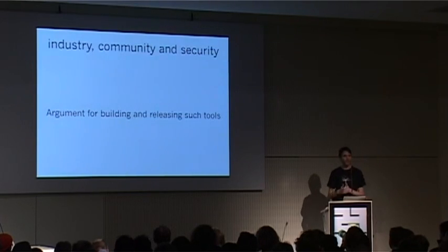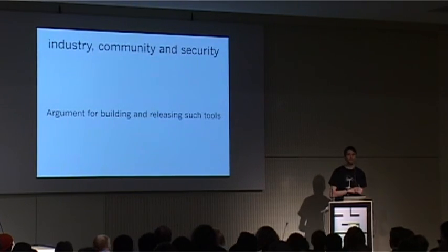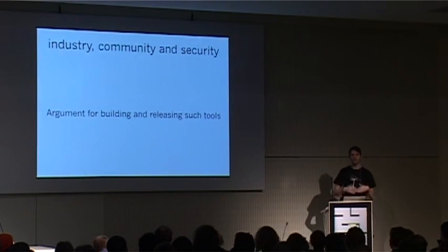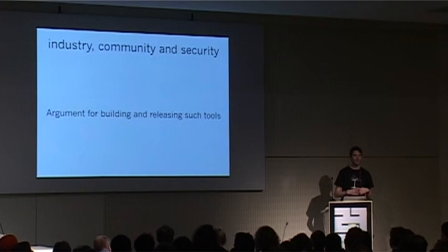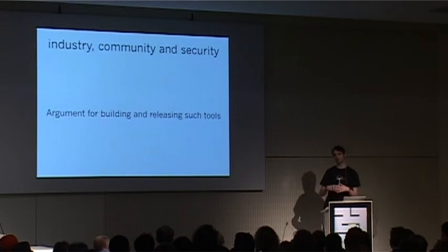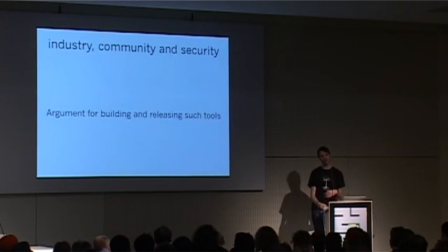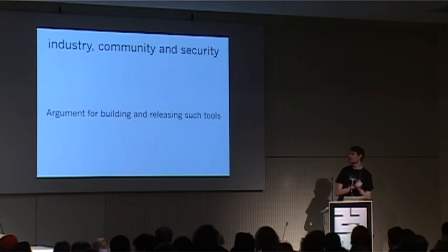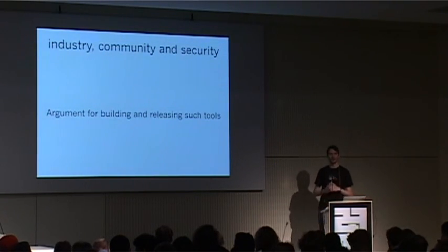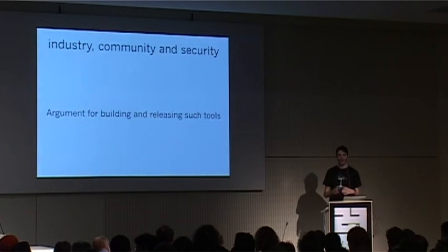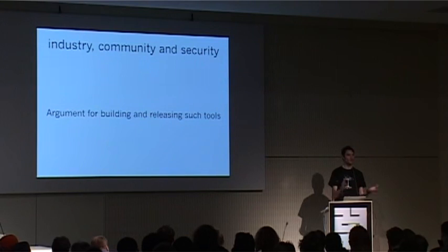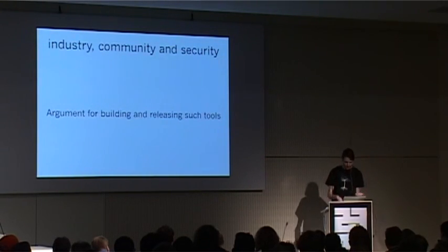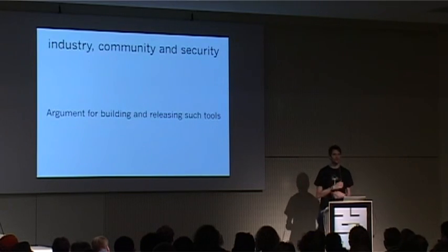Another example is at Black Hat, H.D. Moore presented on the Wind River WDB debug port, which gives you full on-chip debugging of the embedded device. VxWorks was the most popular embedded operating system in 2007, and yet during that whole time, most of the developers left the WDB port open on UDP, so you could just attach to the UDP port and debug the device, dump the memory, etc.